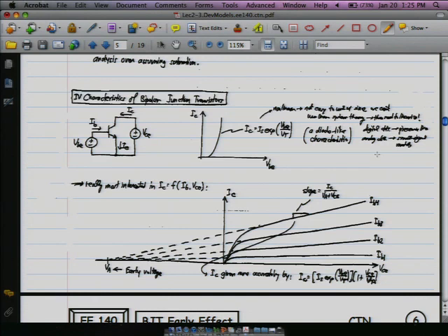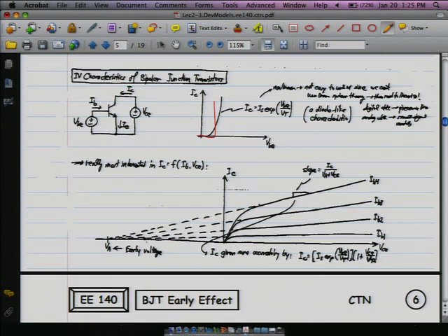If the circuits are digital, then we'll use piecewise linear. The piecewise linear model is basically just the one that says this diode is off until you reach the on voltage, then it's completely on, and you get a straight line up. So that's basically all that means.